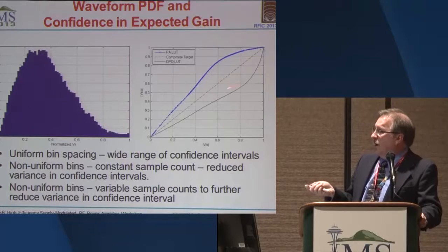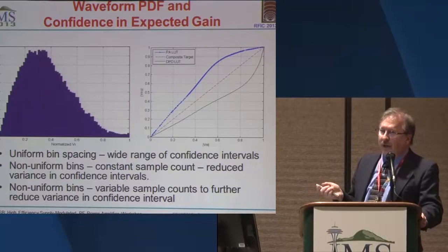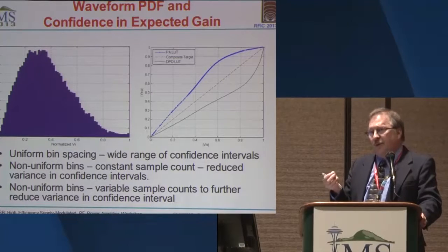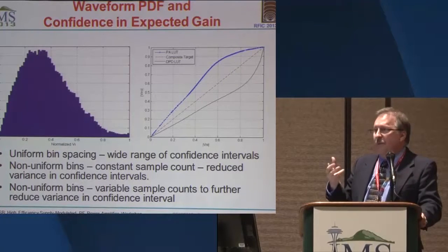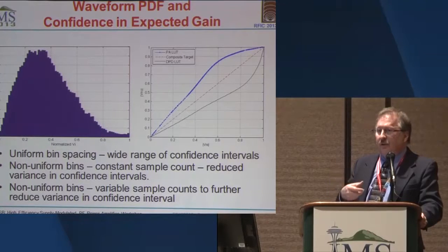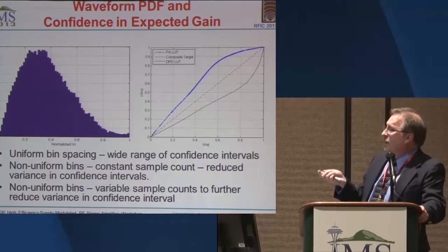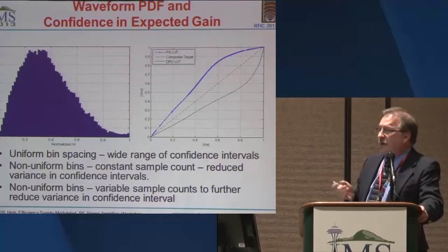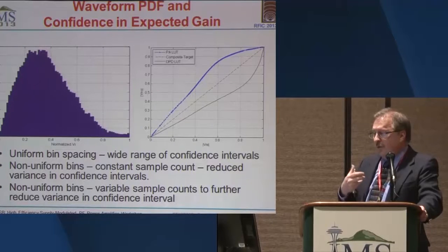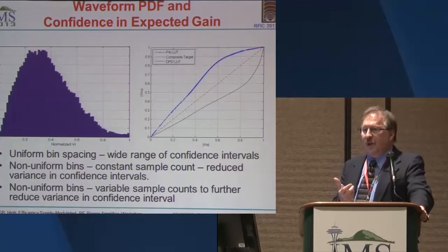And my ultimate goal with digital predistortion is to land on this red dashed line in the middle. I'm able to directly create the predistortion table off of the measurement that has this filtered behavior, or I've filtered the behavior of the measurement and generated directly this compression characteristic here to do crest enhancement, in essence, on the signal that goes into the RFPA.